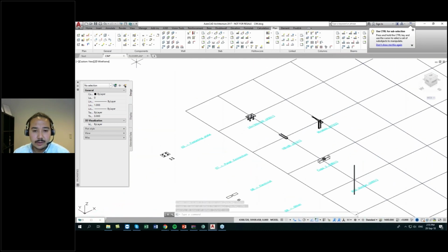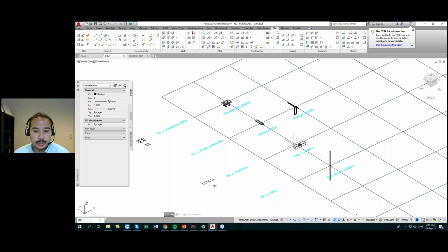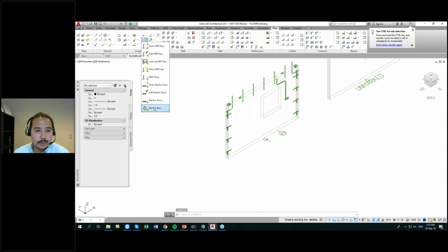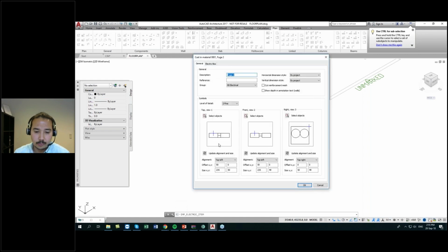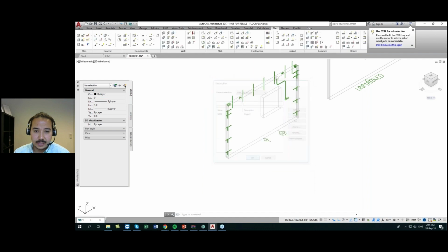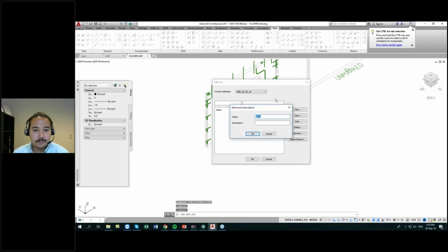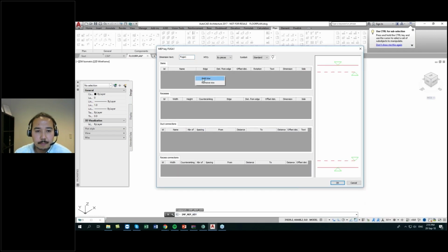So now I've made all my custom materials here, and I will have to insert them into my element, also the MEP key using my MEP key here. So the first thing I'll do is go in here under my electric box and say this one here should reference into the one I already made, so I can find it in my definitions. So when I'm going to make an MEP Key Definition, just call it this. Like this. I go in here and I add, up here on the items, I add my fuga.